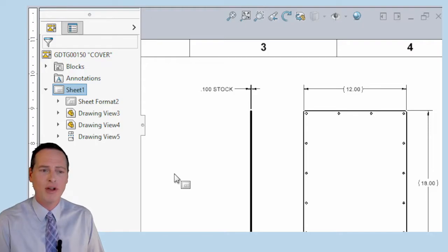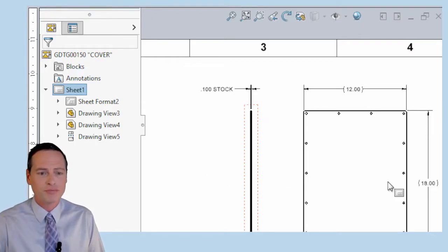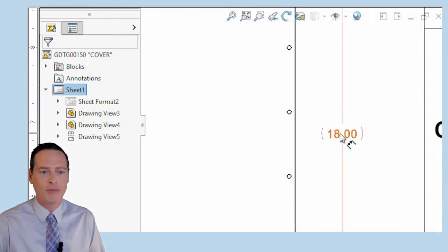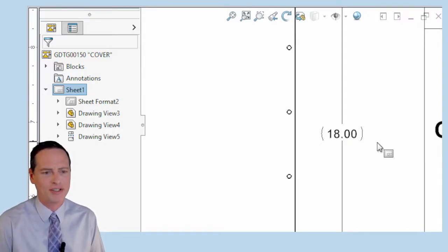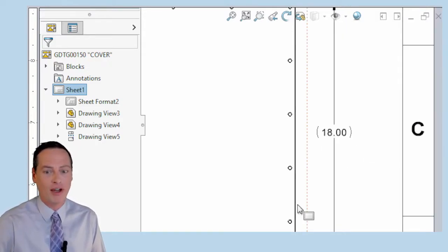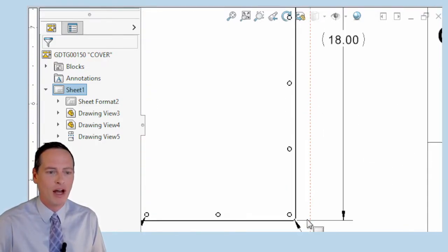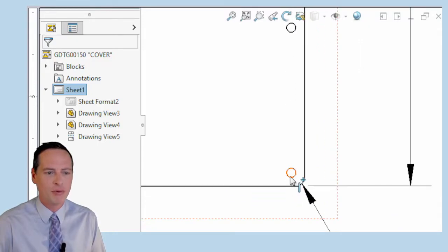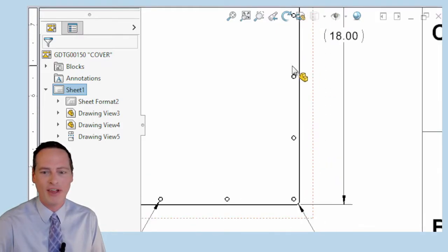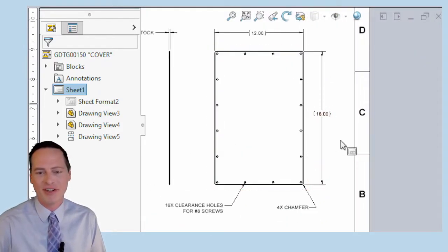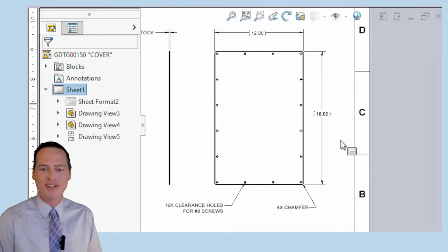It's hard to know what that applies to. Maybe I think plus or minus 20 is not even necessarily a loose tolerance for 18 inches, the way that I want to fabricate this part. So maybe I say, hey, I got an idea. I'll say it's plus or minus 20 from this edge to this hole, and then plus or minus 20 from that hole to that hole, plus or minus 20 from that hole to that hole. And then by the time I get to the other end of the part, I got plenty of tolerance. It's going to be a breeze to make this part.